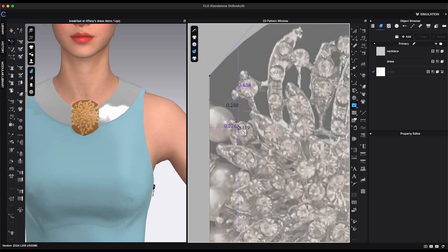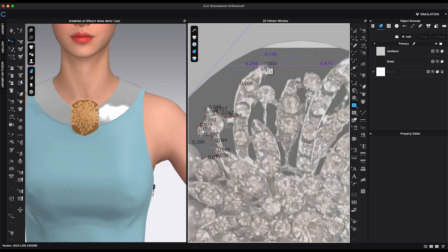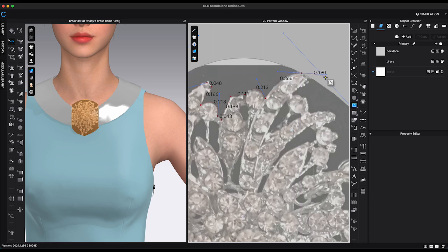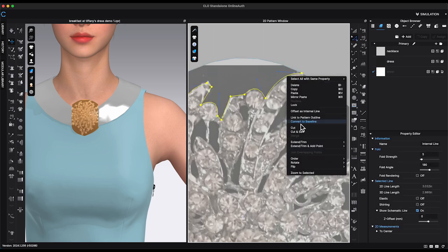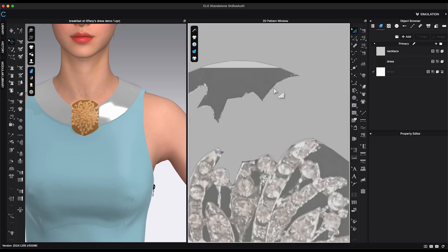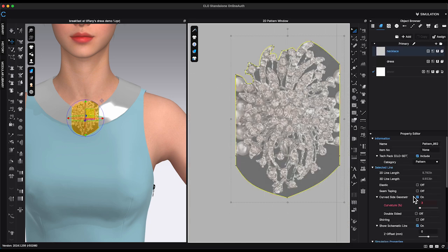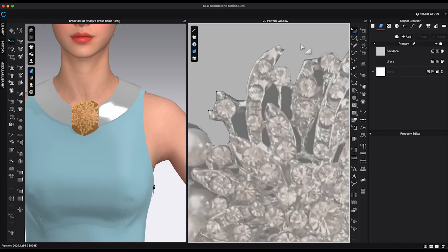Use internal polygon tool to trace the outline of the design and cut out the extra portion. When doing this, I recommend to trace the design by section. It's hard to draw a curved line in such tiny and intricate design. Lowering particle distance to 5 or under will help to get a smoother curve shape.